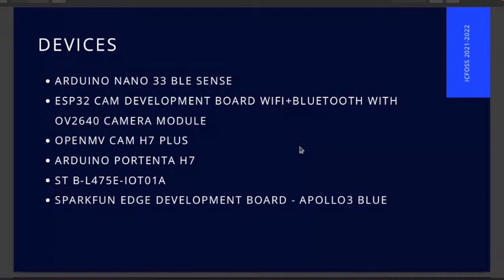temperature, you can use an ESP32, because it is the cheapest sensor, or Arduino, the cheapest board that can sense, process, and send data to the cloud. But if you need to create a device that processes data or runs a machine learning model, it has some limitations. So we need to use devices like this one, Arduino Nano BLE.